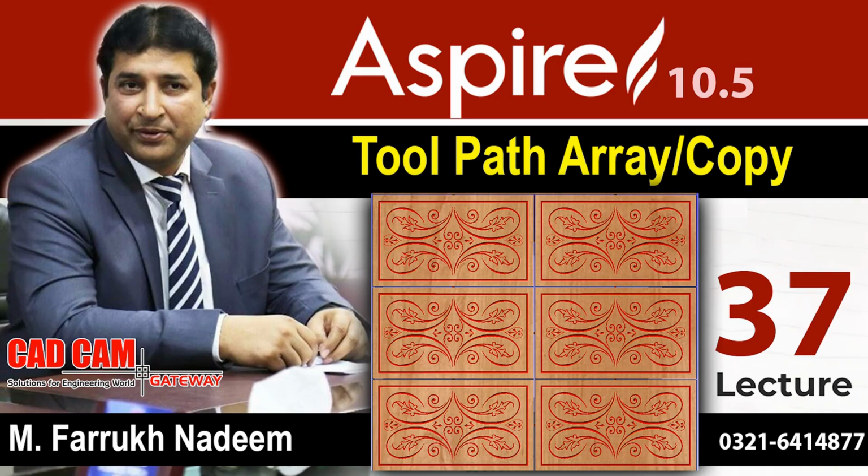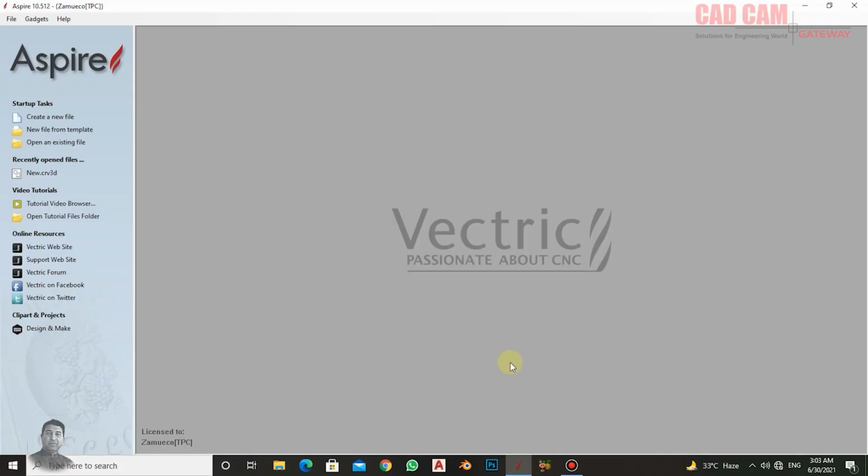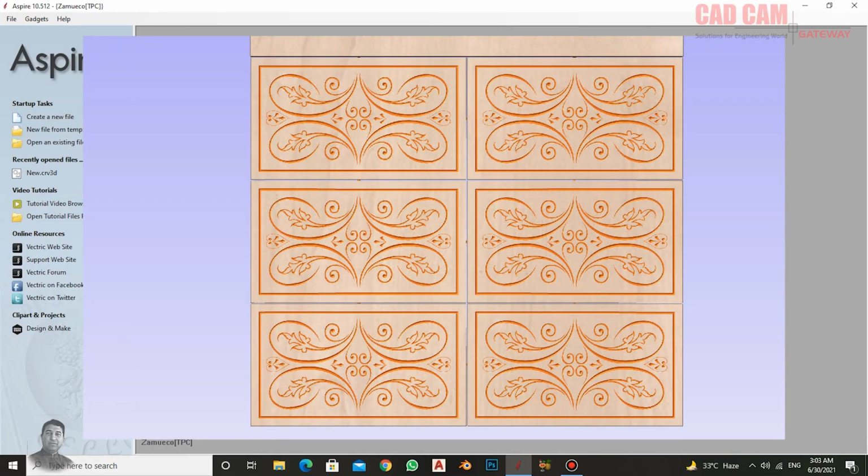Today's topic is very important. Usually, when you create a drawing in Aspire, especially a design that you need to repeat, many people tend to array it beforehand and make as many programs for it as needed. This way, the file becomes very heavy. The solution we have for this is the tool array.